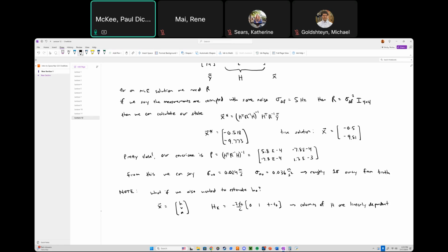So what do we do about that? If your system is unobservable, you don't have a lot of options. You estimate fewer states, or you buy more sensors.